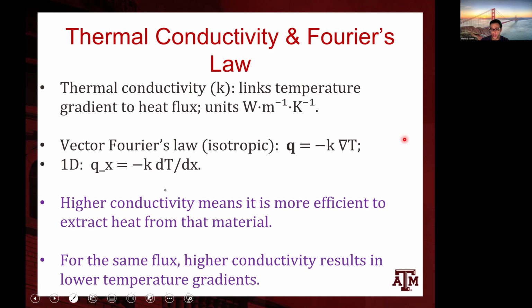And that's very important, as we're gonna discuss in a minute, because the temperature gradient leads to a phenomenon that we call thermal stresses. And if you have very high thermal stresses, then you can fracture or fragment the material. That happens very often for ceramic fuels like UO2 and for ceramic materials in general.